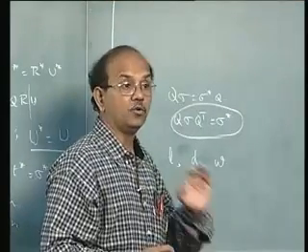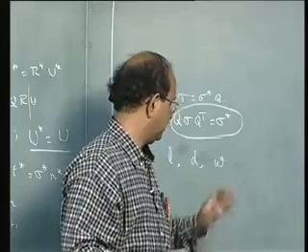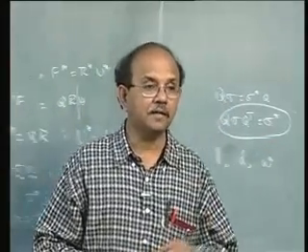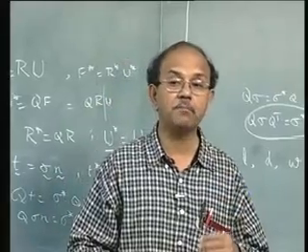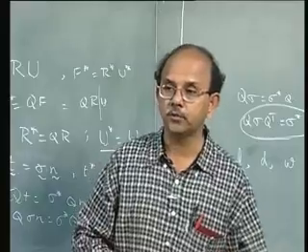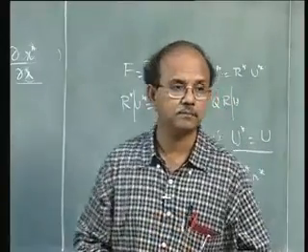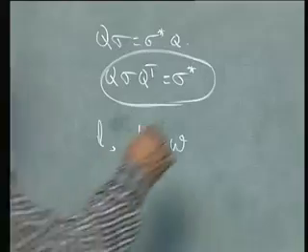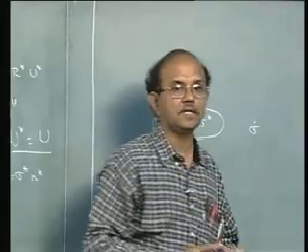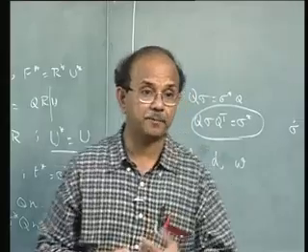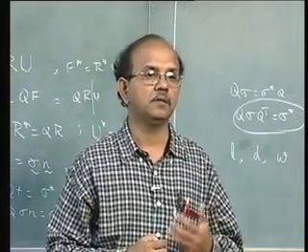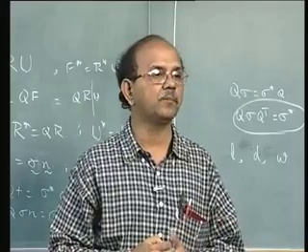And more importantly, even before we go here, we have to establish a simple fact that the rate of stress, sigma dot, is one of the quantities that is extensively used in the constitutive equations. Sigma dot is the time derivative of sigma. These are what are called rate type constitutive equations, very much useful in many circumstances, including plasticity.